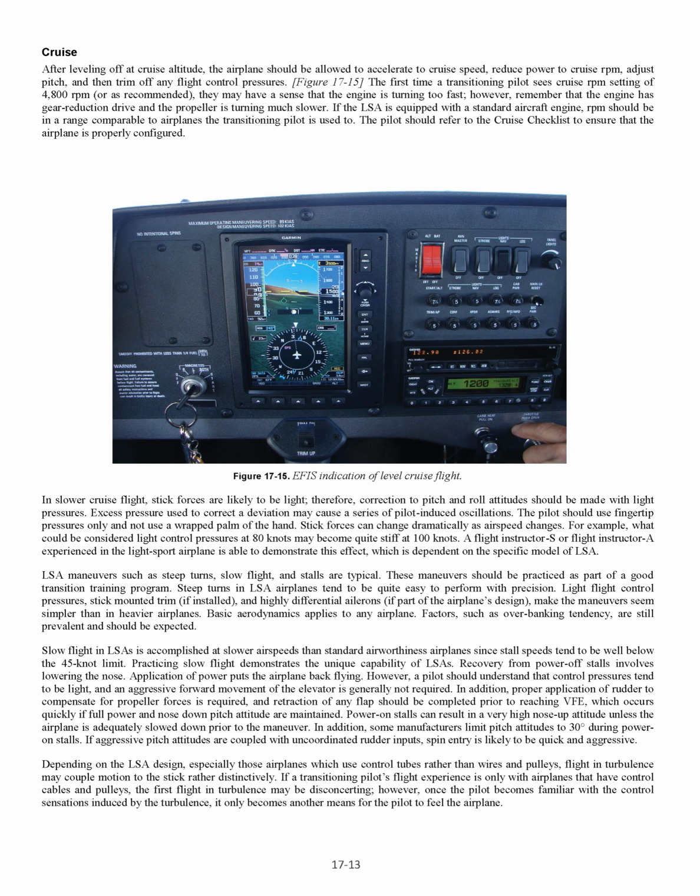Power on stalls can result in a very high nose-up attitude unless the airplane is adequately slowed down prior to the maneuver. In addition, some manufacturers limit pitch attitudes to 30 degrees during power on stalls. If aggressive pitch attitudes are coupled with uncoordinated rudder inputs, spin entry is likely to be quick and aggressive.